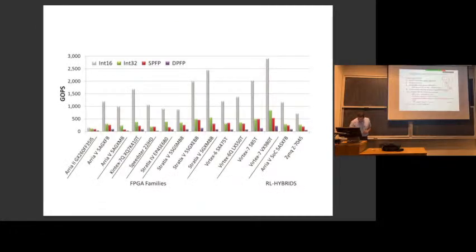For this one, I don't think it specifies how many FPGA resources are used to build a floating point unit. So what they do is they build one floating point multiply accumulate unit. They see how big it is, how much logic, DSP, et cetera, it takes, and then they figure out how many they can fit on the chip. So as they go to a floating point unit, they can't fit as many on the chip, which is why the bar goes down. Their throughput number goes down.